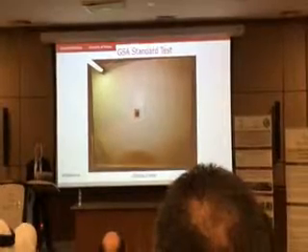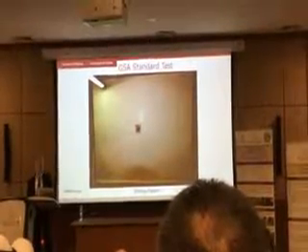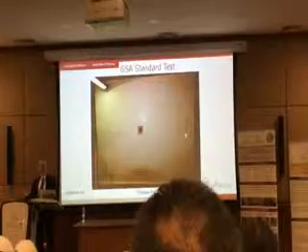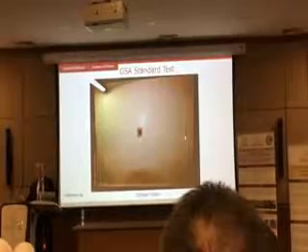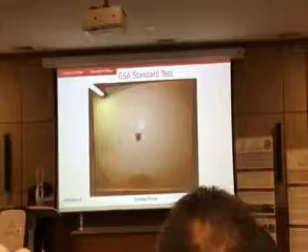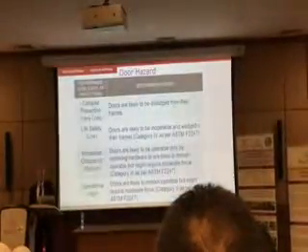So this is the witness panel. You can see all the glass fragments marked, and we subsequently weigh them, and depending on GSA, if it's greater than so much weight, then it qualifies as hazardous glass. So it needed to be glazed with film, security film, okay?